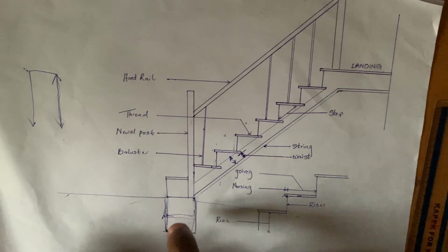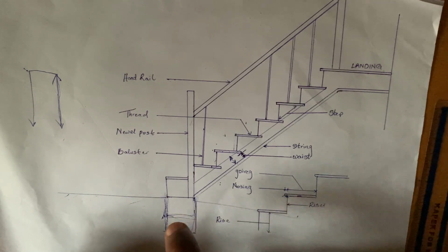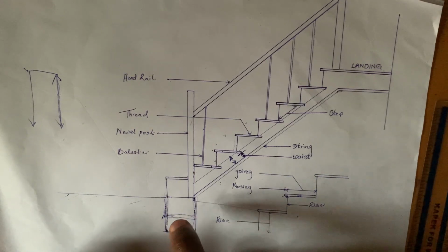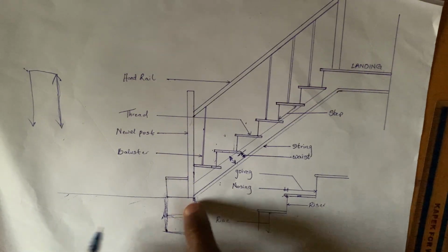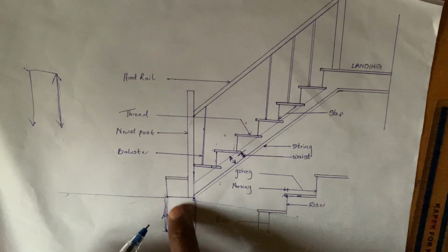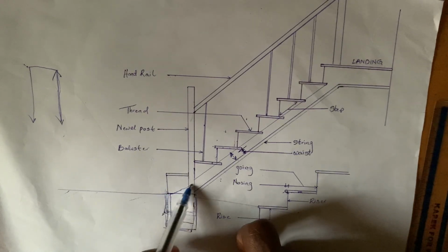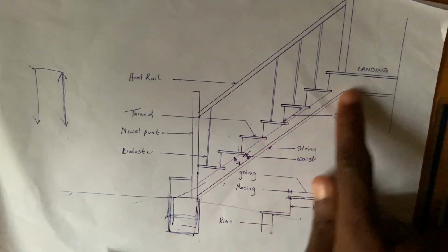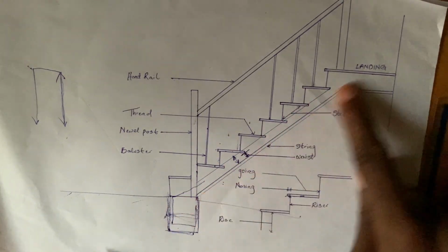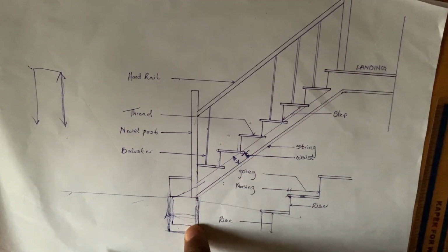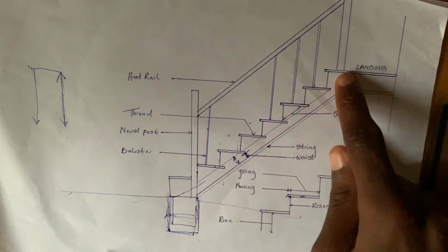Now, this foundation in the staircase consists of reinforced concrete, and this reinforcement in the foundation base is what we call our starter bars. So it is from here that we'll have the reinforcement that will connect the other reinforcements for the staircase running like this. So it is from here that you get that reinforcement, connecting the reinforcement here.